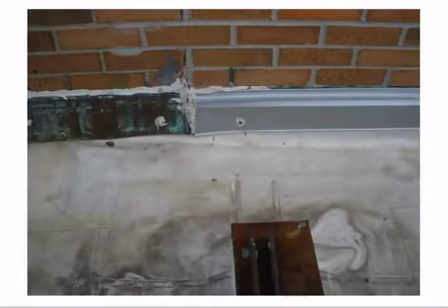Here, it looks to be like we have a pretty similar detail. Yeah, this is similar. They had the basic idea down, with the two-piece counter flashing system again. And there's a couple things going on here. They use some caulk there to bridge that gap as well, instead of overlapping and making a nice watertight system there. But they've also caulked the weep holes, and that will back that water up into that wall, and it'll find its way in and back into the roofing system. Yep, so you want to be really careful there, because in these applications, it could be creating more harm than good, actually, suffocating that wall system. Yep.